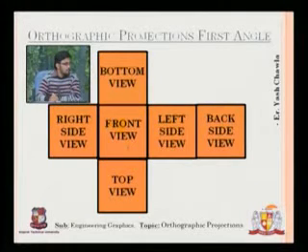And when we are talking about first angle, then we have this top view and the bottom view. The top view will come below the front view and the bottom view will come above the front view. On the left hand side of the front view on your screen will come the right hand side view, and on the right hand side of the front view will come the left hand side view, and beside the left hand side view we will have this back view, as this highlighter is showing.